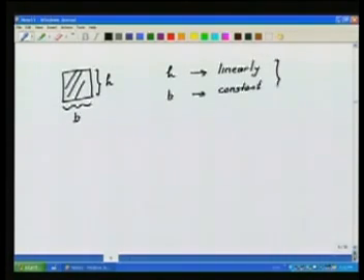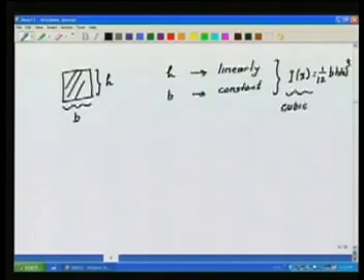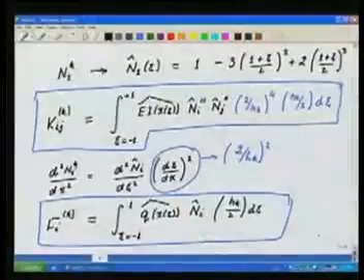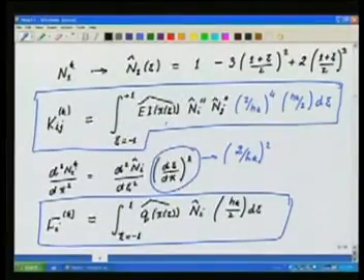So, in this case, I as a function of x is equal to 1/12 b h(x) cubed. So, I varies as a cubic, because h is linear. So, I is 1/12 of bh cubed, it becomes a cubic. So, if I is a cubic, if I go back to my integrand here, so EI is a cubic, it is of order 3.